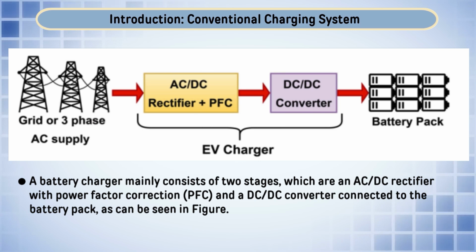vehicle to grid technology. Under vehicle to grid technologies, a number of vehicles can be connected in a pool, and this pool is connected through the aggregator, which communicates with the grid supplier, the power supplier, as well as the customer or the electric vehicles for discharging purposes. The aggregator establishes the communication between these two units, and we can assume 200 or 300 vehicles are integrated in a pool, or a particular power source.